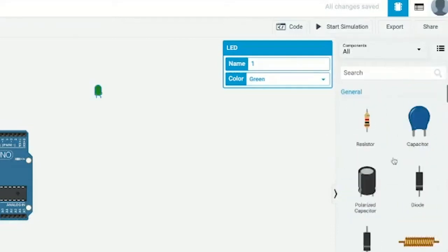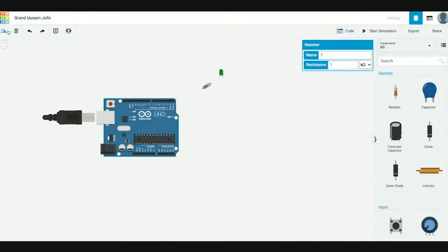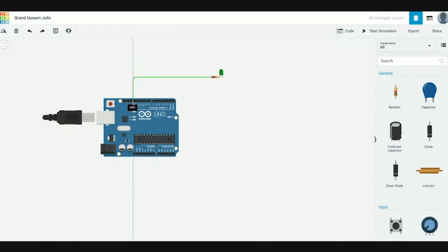Drag an LED from the components bin onto the working plane and practice using the rotate button on the top left-hand side. You can connect components without a breadboard, and for a simple circuit like this, it's highly advised. Just drag the resistor to the cathode leg on the LED and they should connect. Now, from the exposed terminal leg on the resistor, connect this with a wire to ground. We're going to close our circuit at this point by connecting the LED to pin 12.